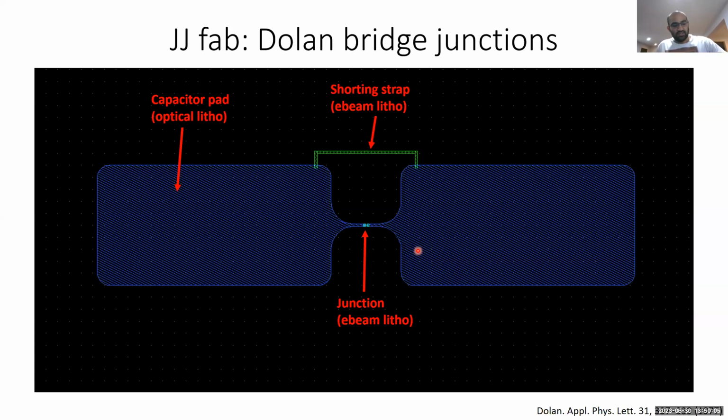There are really no special precautions that we take, except that what we found is that you are most vulnerable to ESD during dicing, so you can argue that the inclusion of a shorting strap is specifically to protect your junctions during the dicing process.